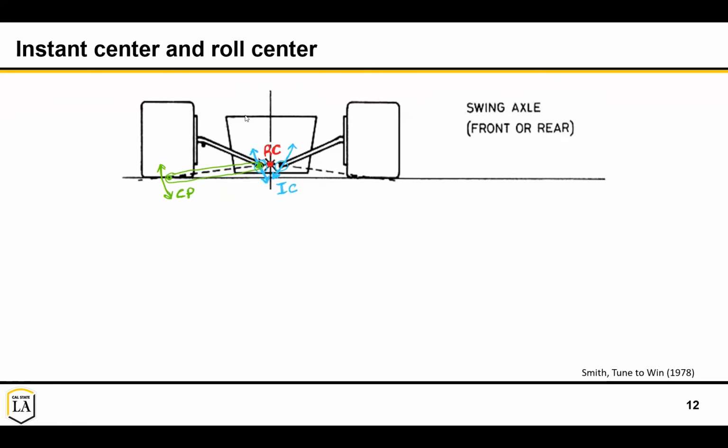we'll call the sprung part of your vehicle because it's typically sitting on springs, it would have to move, if these points were fixed, tangentially to this instant center here and here. So when this actually rolls without moving the tires, you'd extend these lines tangential again here, and you'd get to your roll center, which would be right here. So this is where the vehicle rolls about.